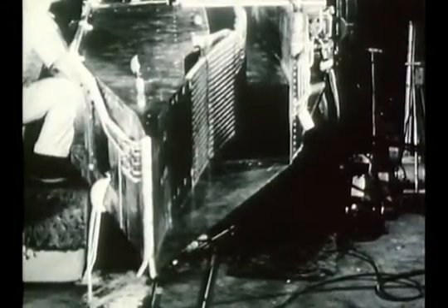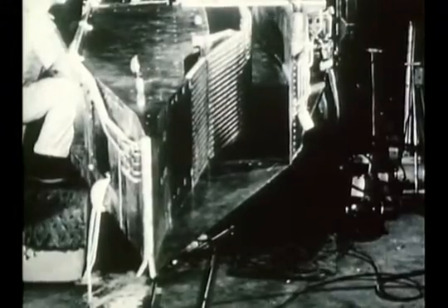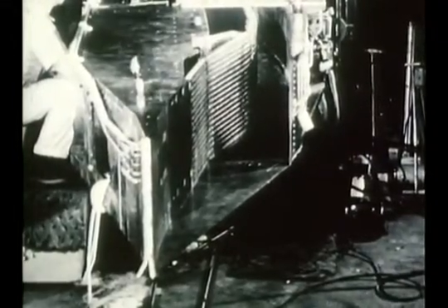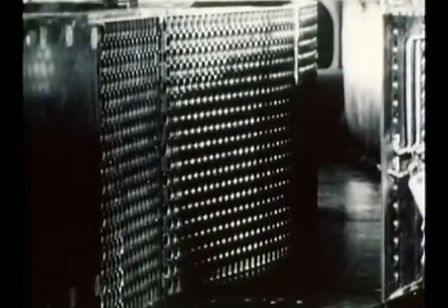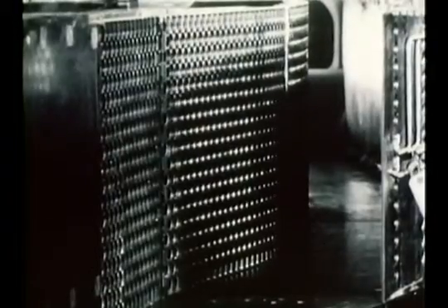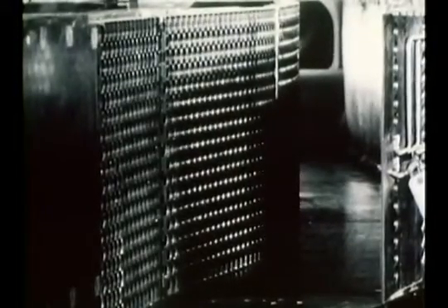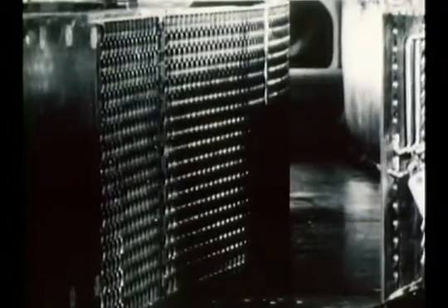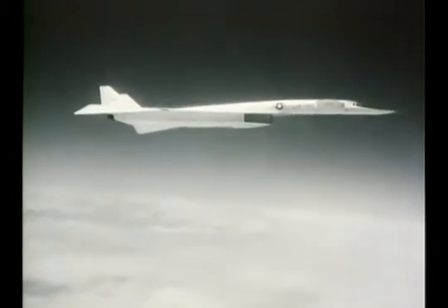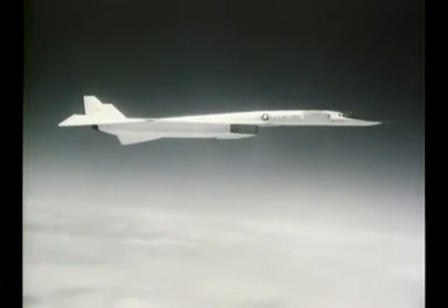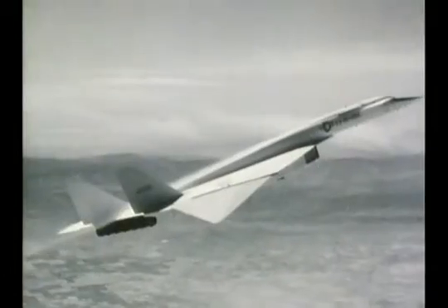This wind tunnel model of the same inlet duct has the top plate removed to show the means provided for varying the geometry in order to improve the pressure recovery. Since the supersonic flow is provided by the relative motion, the inlet duct corresponds to our second throat. However, the idea of a fictitious first throat is still useful for understanding the behavior of the airflow.